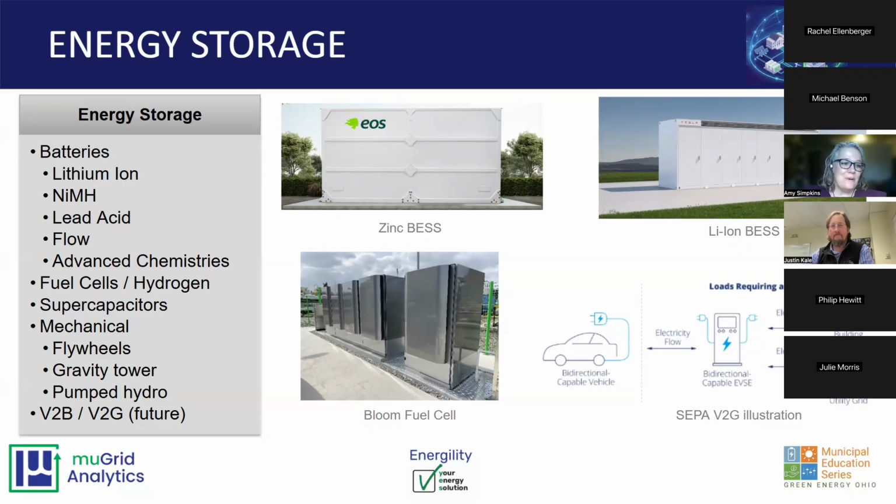Flow batteries are a pretty cool technology that involves a liquid electrolyte that gets pumped back and forth and then charged or discharged as it's pumped between tanks. And so the apparatus to charge the battery and extract the charge from the battery is quite expensive. But once you have that, adding tanks and adding liquid electrolyte is very cheap. And so you can get a lot of capacity in your battery once you've made the investment in that mechanism.